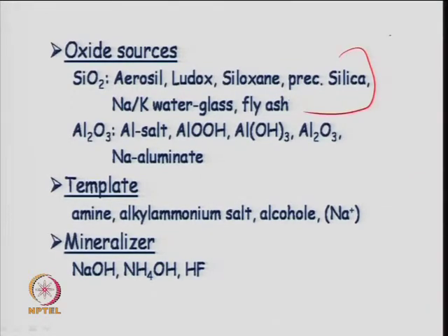It can be a new R&D approach also. Fly ash from, say, a coal gasification plant can be taken, or used zeolites, say spent catalyst. Nowadays a plenty amount of spent catalyst comes. After some preliminary treatment, that can be reused in the process also. Take the used, spent ZSM-5, just grind it, give it the proper pre-treatment, and then reuse it in the process. So, that can be another R&D option for this.